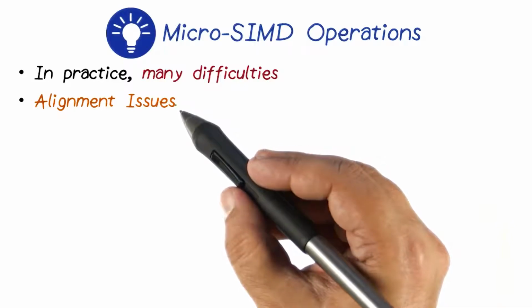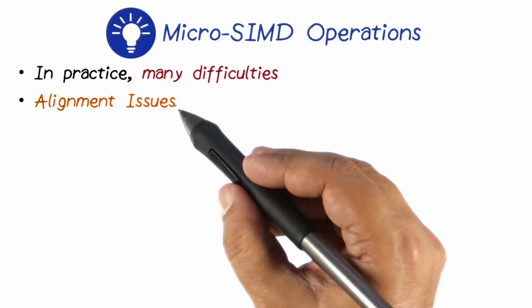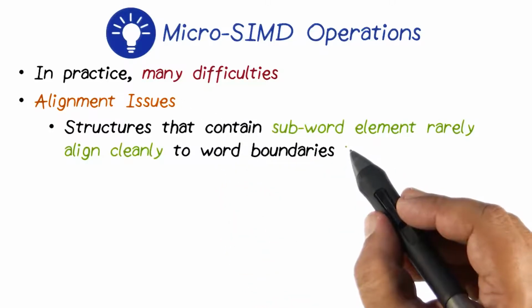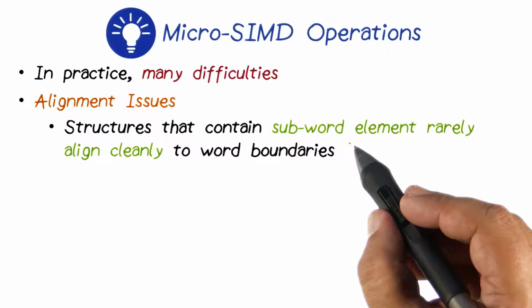Alignment issues. That means, remember, the data has to be on the right word boundaries, and that's always assured by an architecture. But now, if you're breaking the data into subwords, one must make sure that the data is aligned on subword boundaries. So one of the difficulties is that many times the structure that contains the subword elements rarely align cleanly to the word boundaries. In rare events, the decomposition of a word into subwords is as clean as taking a 64-bit word and cutting it into two 32-bit words.